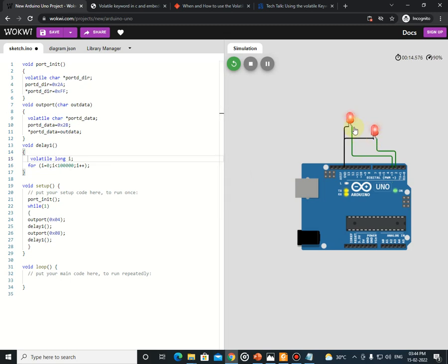This is the use of volatile in hardware or embedded C, and you can use it anywhere, but this is the basic usage of volatile. Whenever you are going to deal with registers and their addresses, better use volatile. You cannot know when the values of the registers will be changed, it is unpredictable. So you can use volatile in that area.